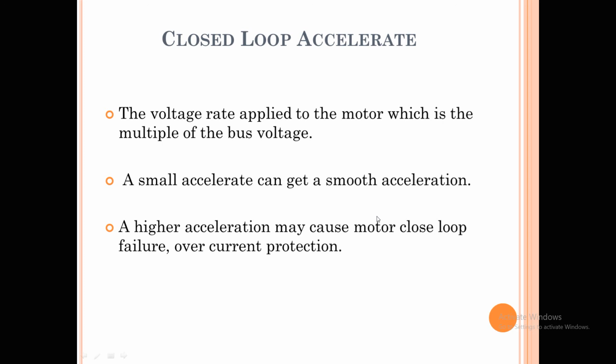Different manufacturers can provide different parameters for these values. Now if you select a smaller closed loop acceleration value, it means your motor will start smoothly.